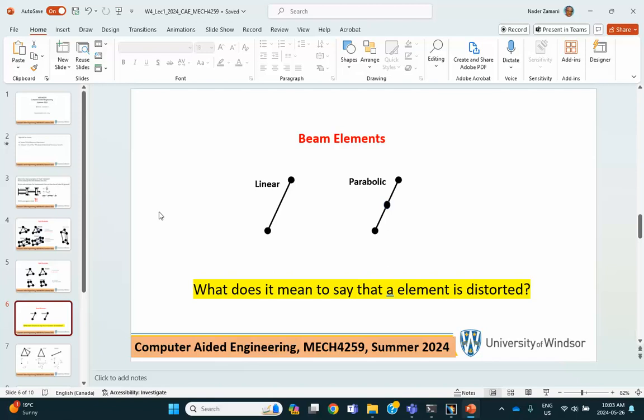Yeah, you might say, well, can I not solve that thing with shell element? The answer is yes, you can. But if you're interested in getting deflections and natural frequencies, then beam element will do, with the cross section being that square that you see in the diving board. Or, for example, your I-beams that are supporting roofs and columns are, generally speaking, modeled with beam elements.